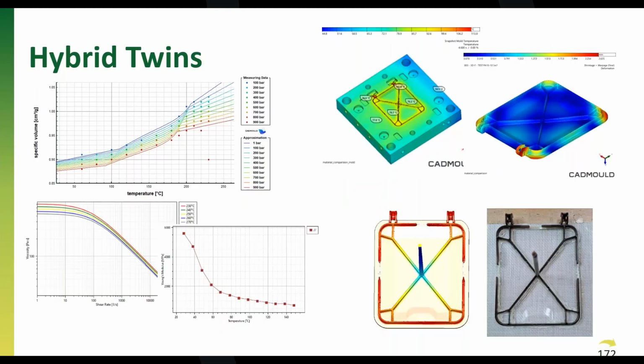Thanks to this characterization, we were able to make some deformation estimation of the product. Also thermal analysis of the mold during the production that we can see, and most importantly, the filling pattern could be estimated and the part validated for production. Next slide, please.